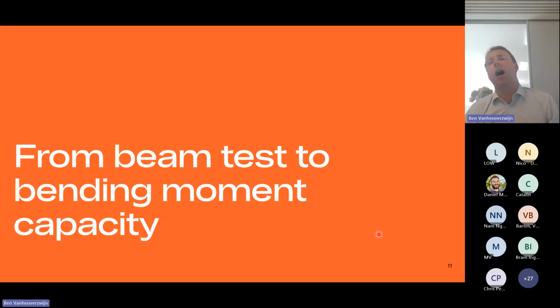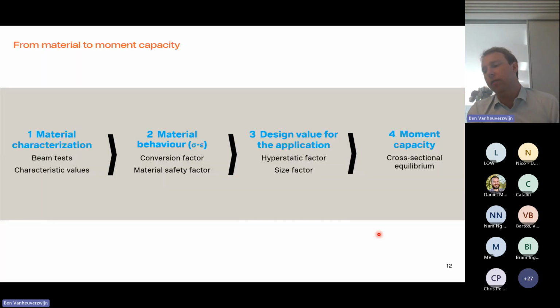So how are we now dealing with fiber concrete in our structural design? There are a lot of standards, norms, and guidance documents available nowadays to design concrete with. One of the most used ones is the Model Code 2010. Nowadays, we also have the new draft version of the Eurocode, where we have an Annex L, which allows us to design fiber concrete for structural applications.